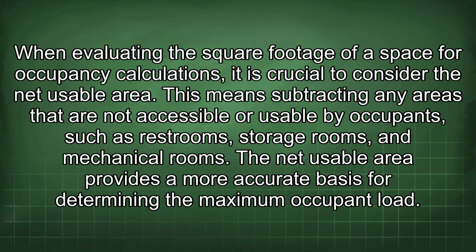When evaluating the square footage of a space for occupancy calculations, it is crucial to consider the net usable area. This means subtracting any areas that are not accessible or usable by occupants, such as restrooms, storage rooms, and mechanical rooms. The net usable area provides a more accurate basis for determining the maximum occupant load.